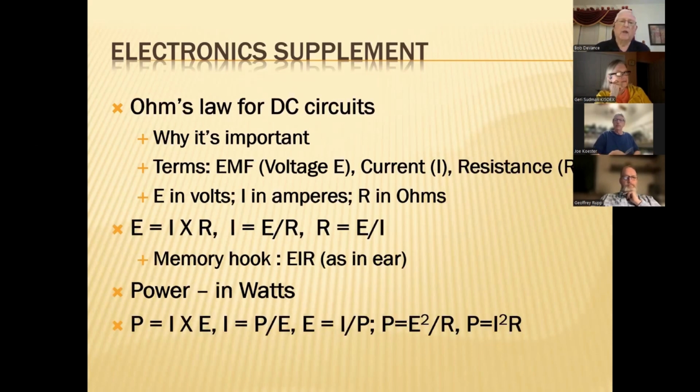Okay, Ohm's law. We need to have a little bit of Ohm's law in our background because that's the main thing that we use for figuring out what's going on in any given circuit. It lets us know about the voltage, the current, the resistance that are there, and how they interact. A certain amount of voltage will push a certain amount of current through a certain resistance, and we can calculate what those things are ahead of time and see if we're going to overpower or overdo some circuit, see if the circuit can handle what we've actually told it to do.